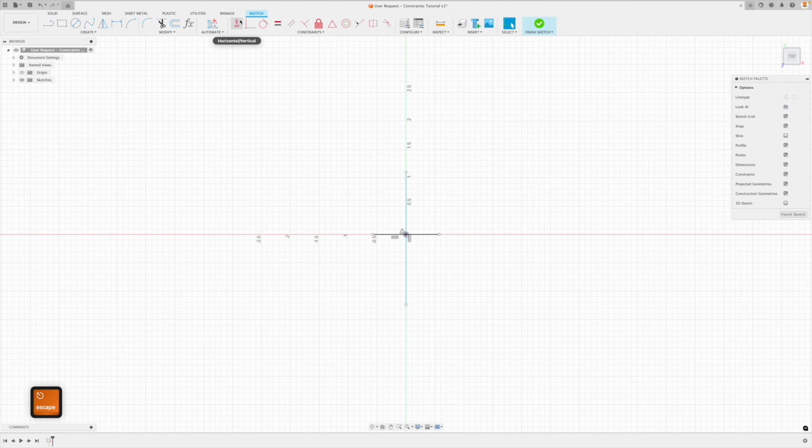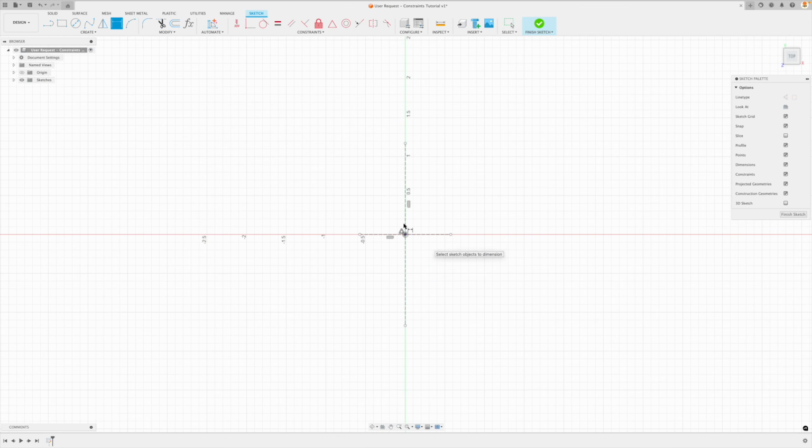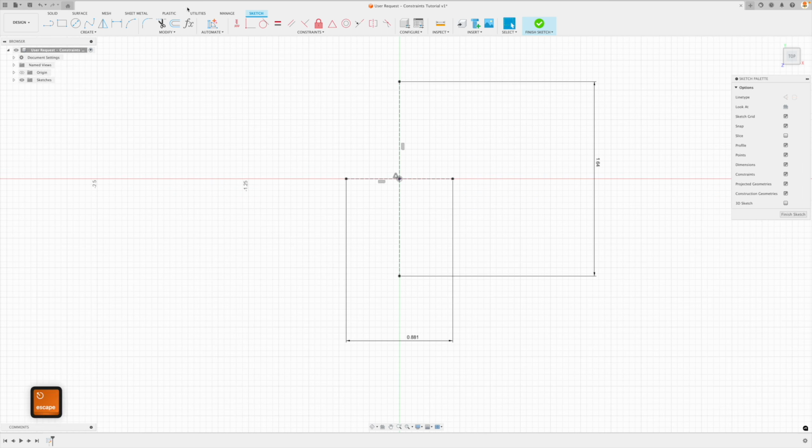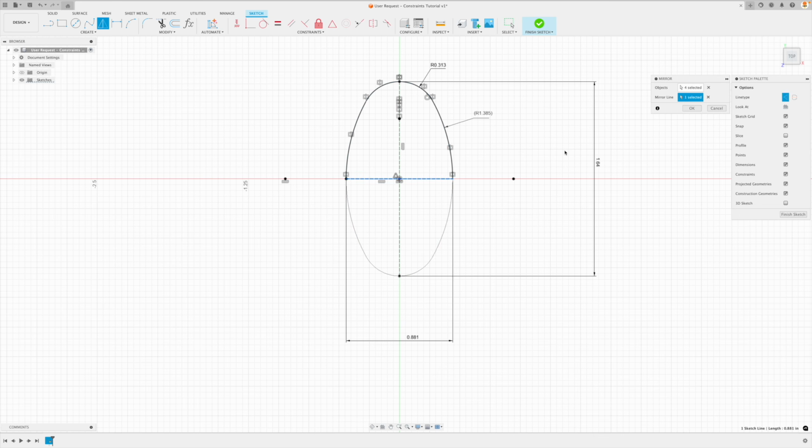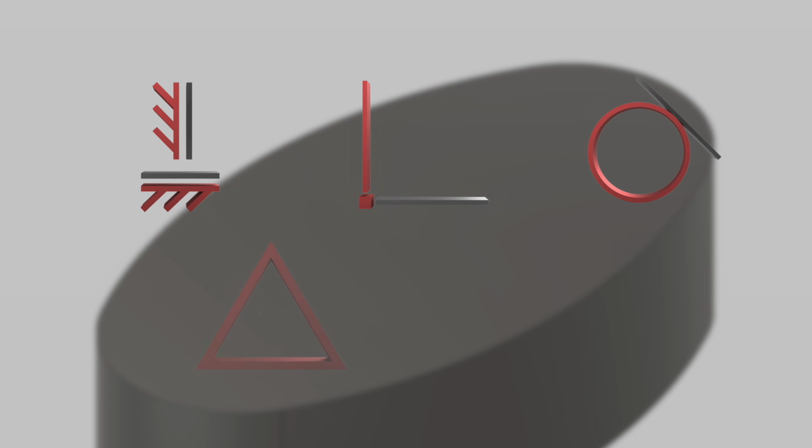In this tutorial, you will benefit greatly from a beginner's request for help with the part he was designing. Designing that part will be fairly simple, but understanding why and how we use constraints is a bigger subject that needs to be learned. Therefore, join us as we discuss how to use the vertical, horizontal, coincident, tangent, midpoint, and symmetry constraints along with fundamental mathematical expressions in this tutorial brought to you by the Learn It channel.